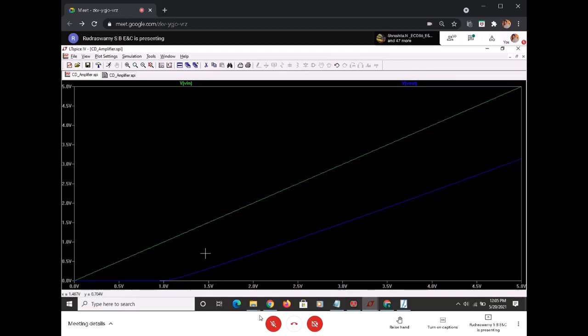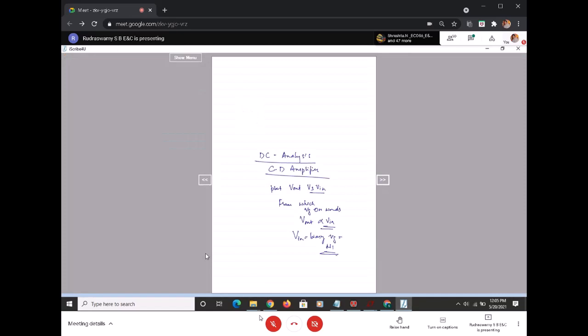So that's why we ensure that V in is somewhere around 4 volts, the DC bias. This is all about the DC bias I'm saying. The biasing of M2 should be less than V out, and we have taken 0.8 or 0.9, and the biasing of M1, which is V in, I'm now considering as 4 volts. You can even take 3.5 volts and see. The better the biasing voltage, the better the output in terms of the input.